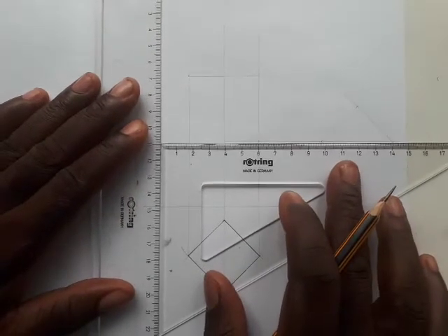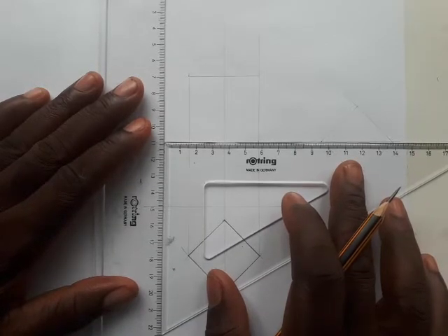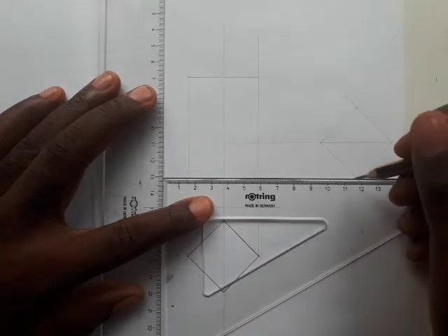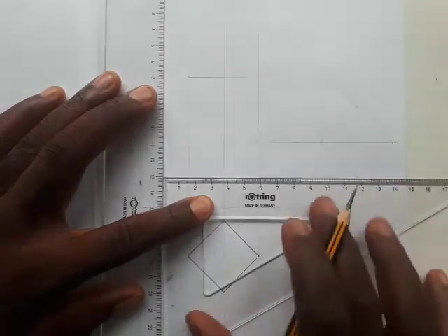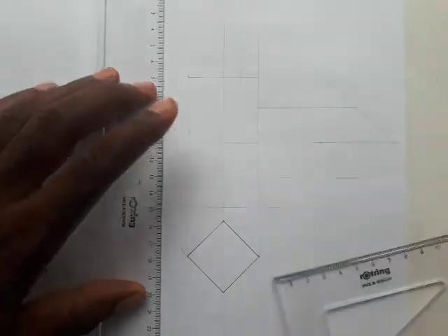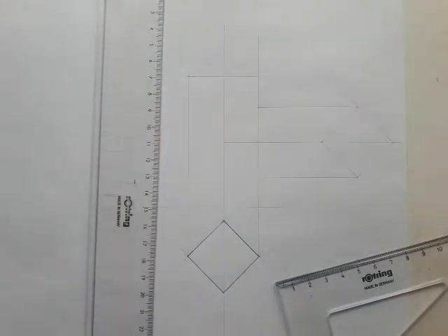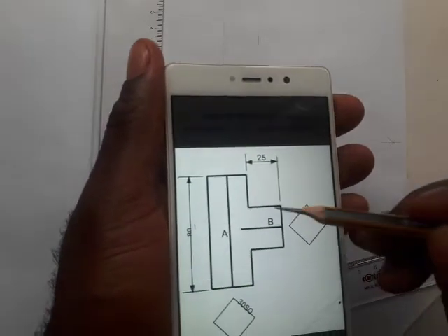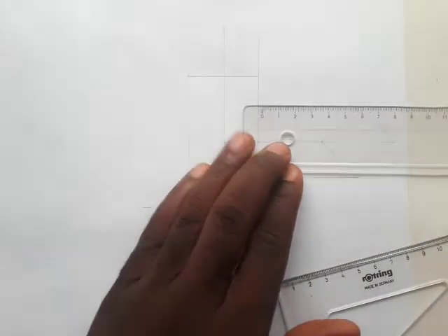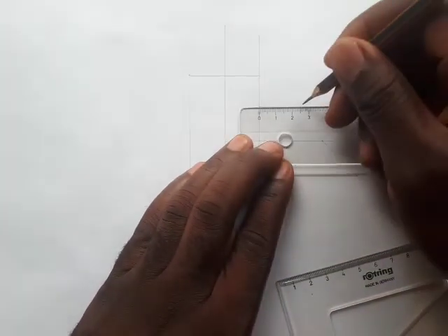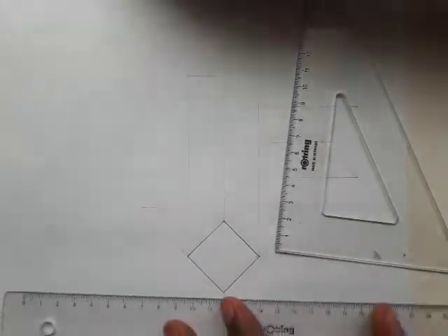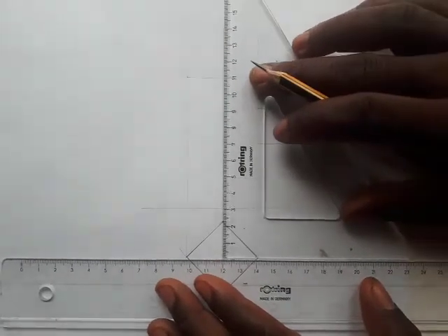So I'm going to align my set square with this horizontal line, slide down to this point here and draw a thin line to meet this pipe, slide up, draw from here thin lines to meet this pipe. I hope that's clear. Now we're told that the distance from here to here is what? 25. So we're going to measure 25. That's 2.5. So this is 0, this is 2, and this is 2.5. That's it. So I'm going to align my set square in this form with any of the vertical lines here.